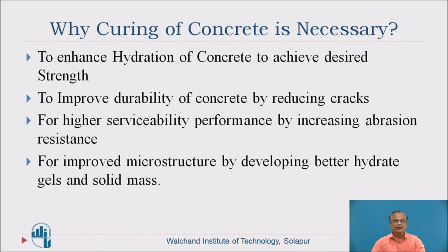In a nutshell, we can say it is necessary to enhance hydration of concrete to achieve desired strength, to improve durability of concrete by reducing cracks, for higher serviceability performance by increasing abrasion resistance, and for improved microstructure by developing better hydrate gels and solid mass. So these are the important points which are taken care of in curing of concrete, and for these reasons the curing becomes necessary, remember.